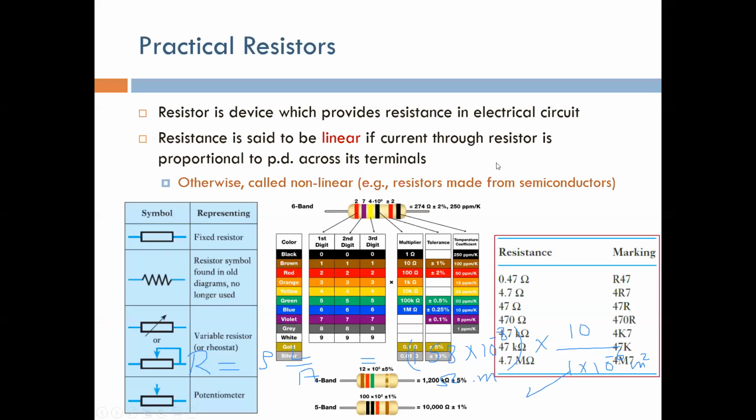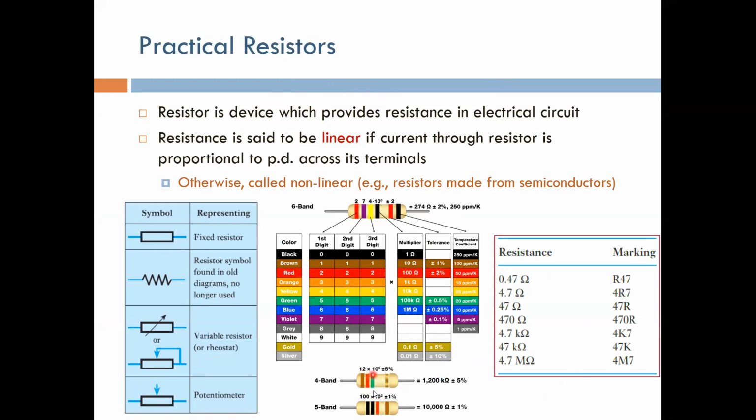So now we're going to start talking about some things that are kind of new. They are not very new, but many parts of them will be a little bit new to you. For example, the practical code for resistors. If you have a resistor with 4 bands, we know how to calculate its value. We take the code for the first and second bands and make a number, then multiply by 10 to the power of the value of the third color, and the fourth color will be the tolerance, right? You saw that before.